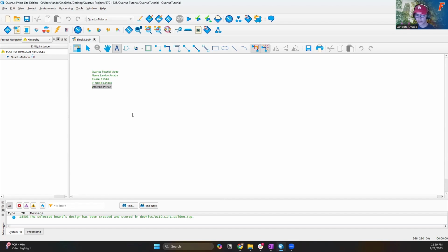Since we'll go ahead and make a half adder in this video, I'll say half adder. Since a half adder is a very common component, you can leave it there. But as you get to some more complex designs, it wouldn't hurt to add a little more description. So if you think about how binary addition works, if you add 0 and 0, you'll get 0. If you add 0 and 1, you'll get 1. And I can also write this out so it's a little more clear. 0 plus 0 is 0. 0 plus 1 is 1. 1 plus 0 is 1.